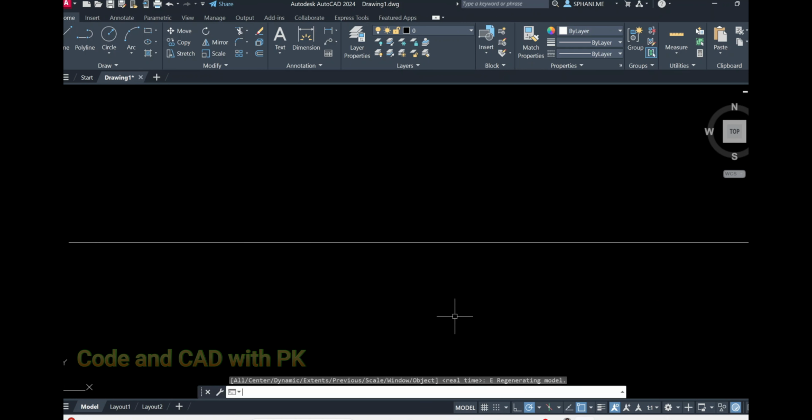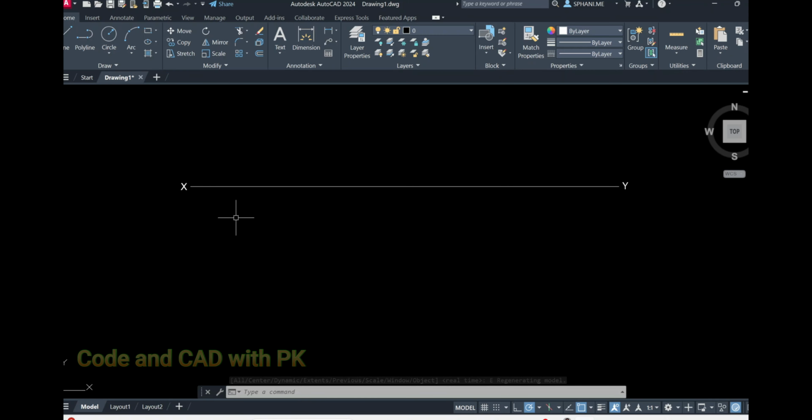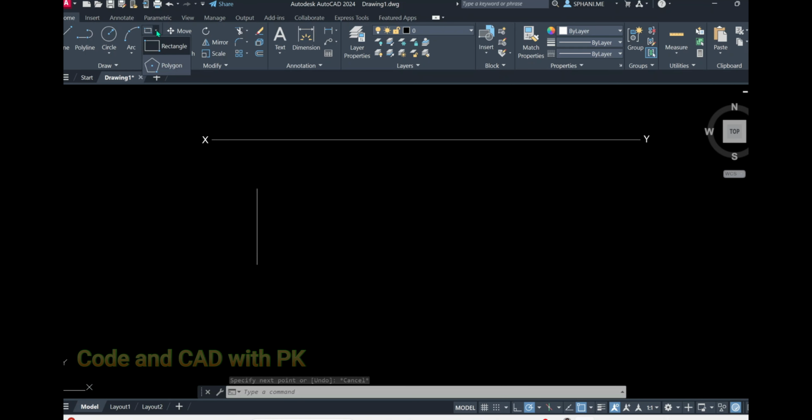Next, draw the top view. To draw the top view, use the pentagon. First draw the edge, it is 45. Now using the polygon command, number of sides 5, enter, select edge. Now select your edge, pick endpoints. After that you just remove the style.